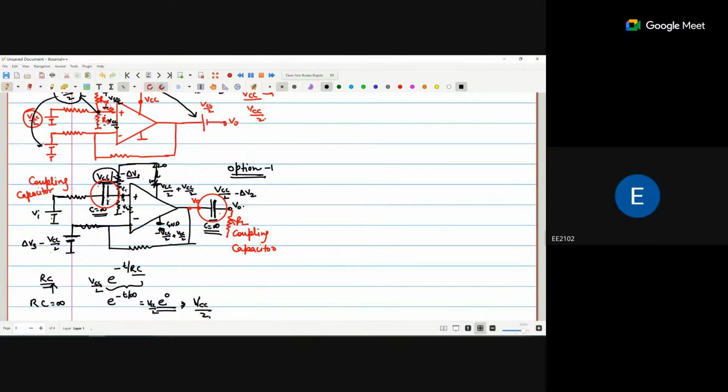First, the input side, the input voltage that we are getting from some other circuit, we use that input to this operational amplifier. We can use this Vi as an input, that is DC as well as the AC signal. So the signal will be fed into the operational amplifier. So we couple our input signal into the operational amplifier, so we require one coupling capacitor. Similarly at the output we connect another stage, also an operational amplifier, to increase the gain or for other applications.